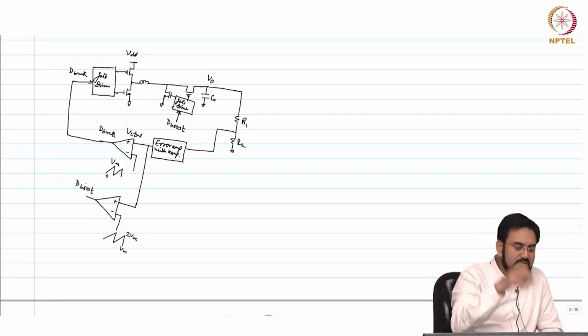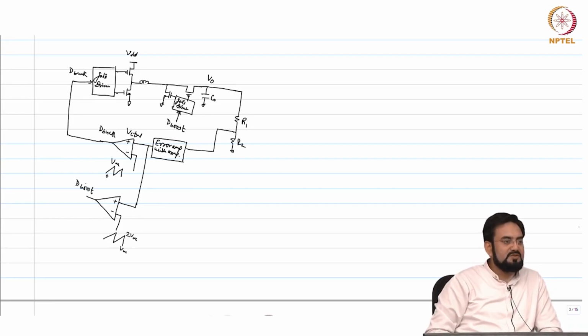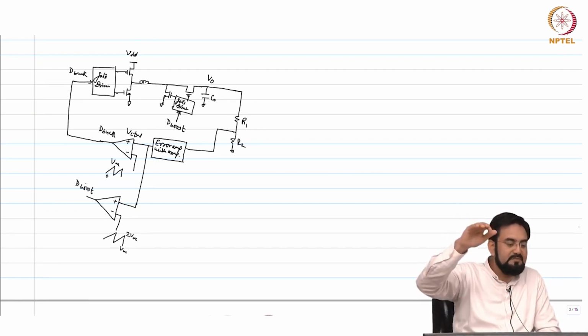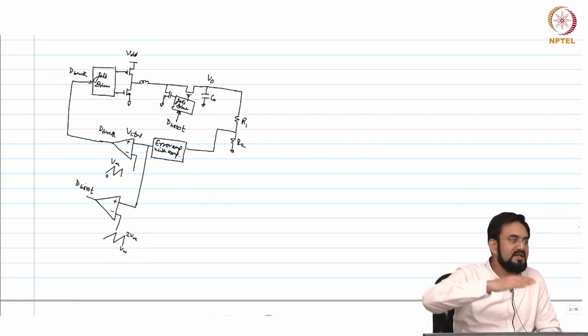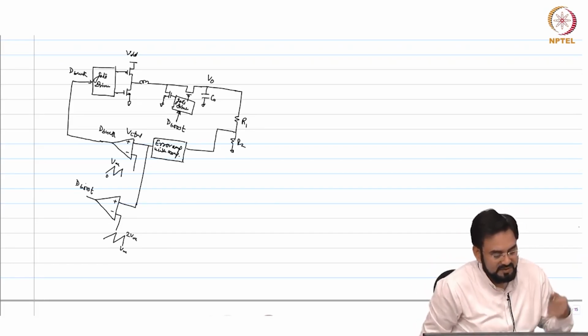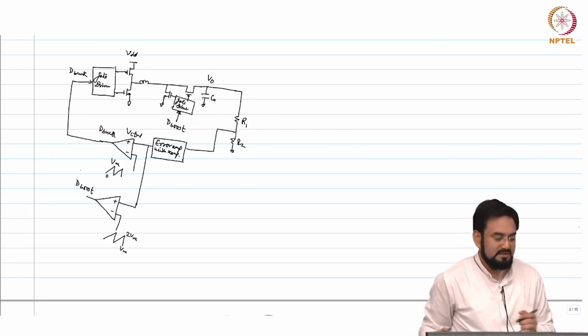So which means your boost sawtooth has to start from Vm. So at Vm your boost will be 0 duty cycle, and when it further increases, goes beyond Vm, it will start increasing the boost duty cycle, and when it goes to 2 Vm, it will become 100% boost.